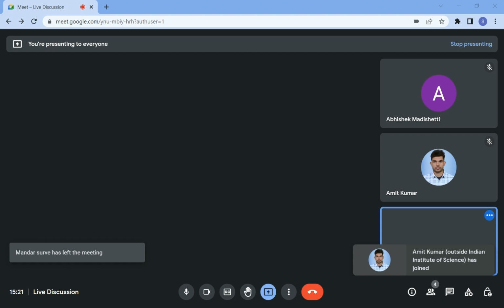B2, let's call this. So A B2 is the true length because that's what I mark, and B I know will always be on this locus. So now if you measure this angle theta, this will be equal to the true angle with respect to HP.